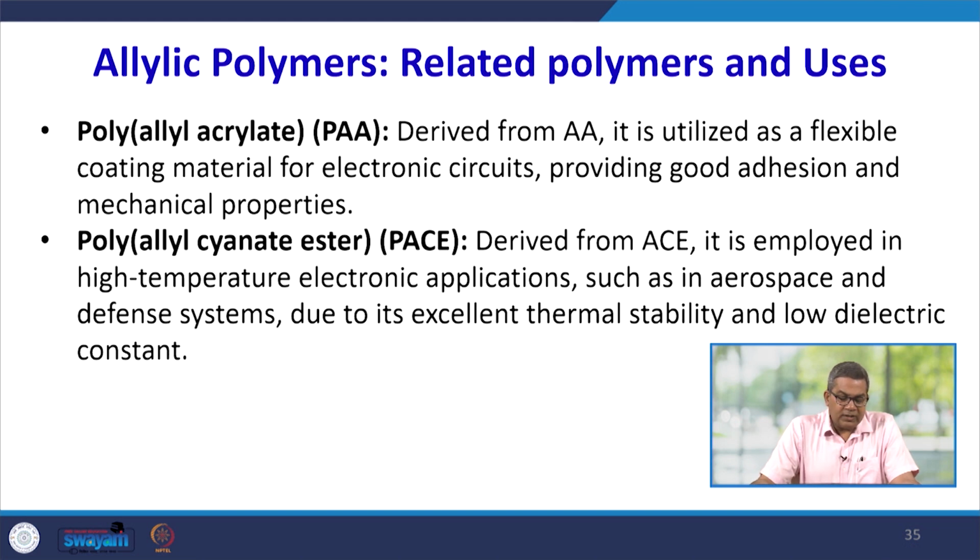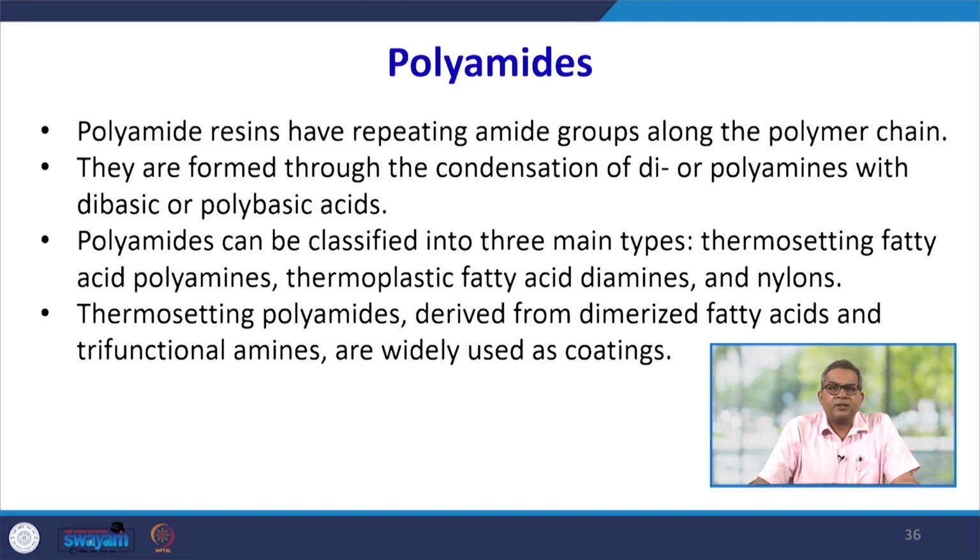Then polyallyl cyanate ester. This is again derived from allyl cyanate ester, and it is employed in high temperature electronic applications like aerospace and defense, because of its excellent thermal stability and low dielectric constant. Let's talk about the polyamides.